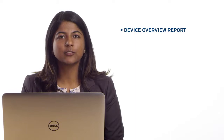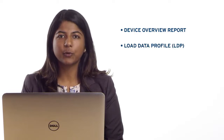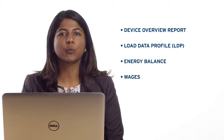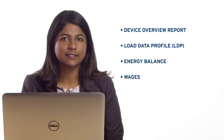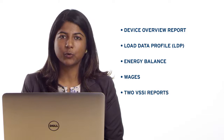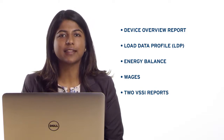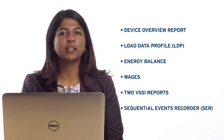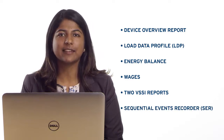The 7 predefined report templates are the device overview report, load profile, energy balance, WAGES, which stands for water, air, gas, electricity, and steam, 2 VSSI reports, which stand for voltage sag, swell, interruption, the summary and detail, and the sequential events recorder, that's the SER.